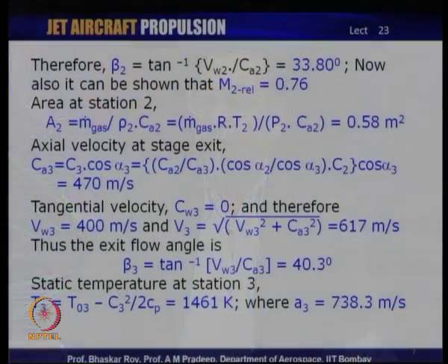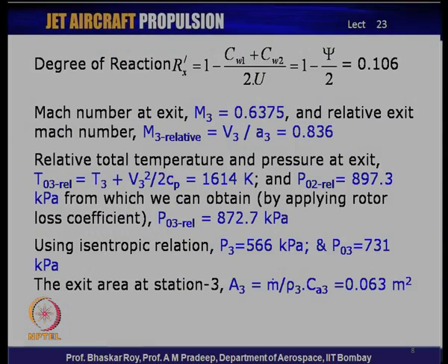Most turbine designers would like to avoid that kind of complication in their turbine design, because it would impact the aerothermodynamic efficiency, or what we call the isentropic efficiency of the turbine, quite adversely. So, as we see by the numbers, they are deliberately kept subsonic. Let us proceed with this problem and see whether we can complete it.